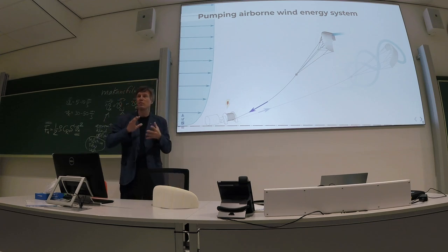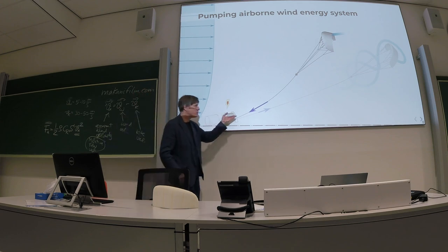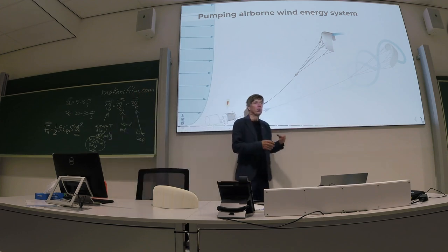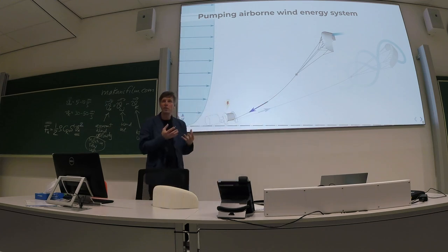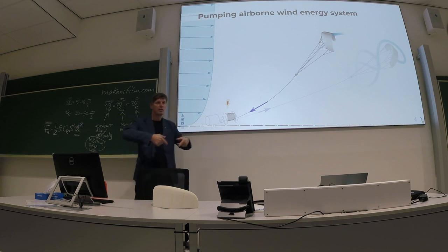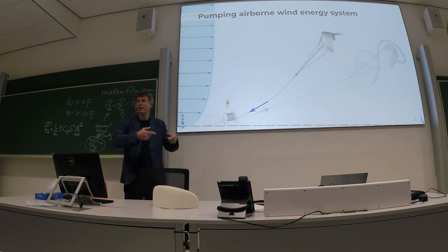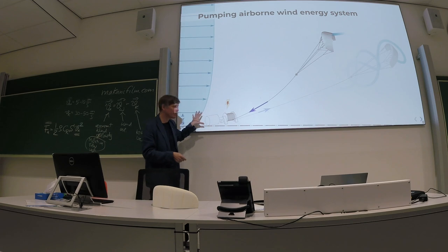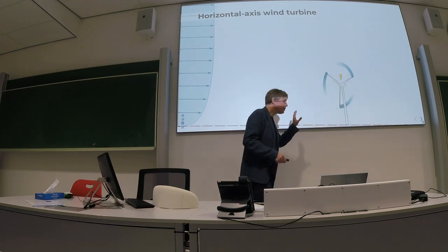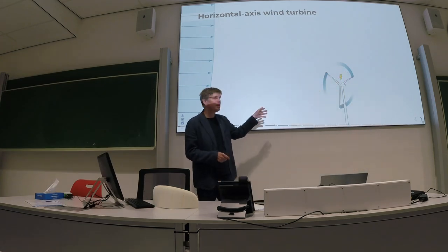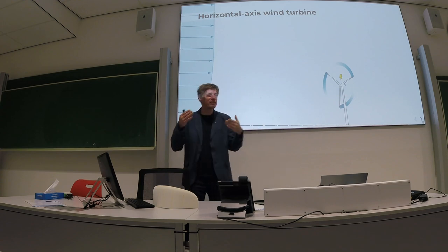You have a combustion stroke, which generates energy, and a compression stroke, where energy is used, and the energy is stored in the kinetic energy of the crankshaft. The crankshaft equalizes the cyclic operation, and in our system we use a rechargeable battery.